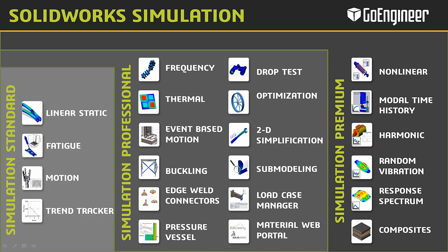Now, what tools did we leverage today? We've leveraged just one tool, which is SolidWorks Simulation, that has each of these flavors distributed in 3 levels. There's a standard, professional, premium level. Now, the standard gives you all the static and durability testing. The professional gives you optimization and thermal and frequency analyses. And finally, the premium is where you get into the nonlinear and vibration aspect of the analysis tool.